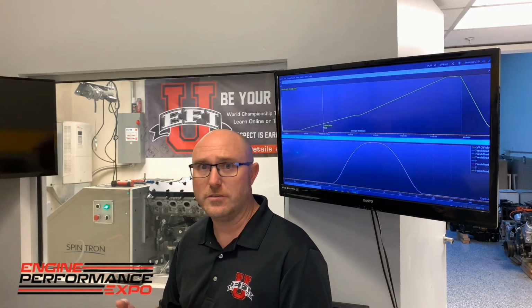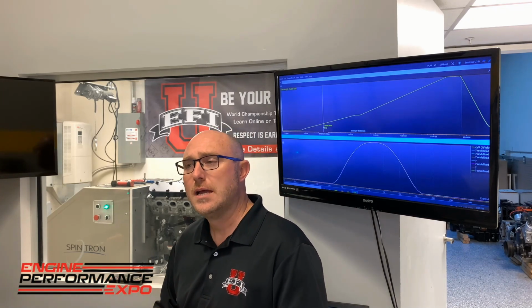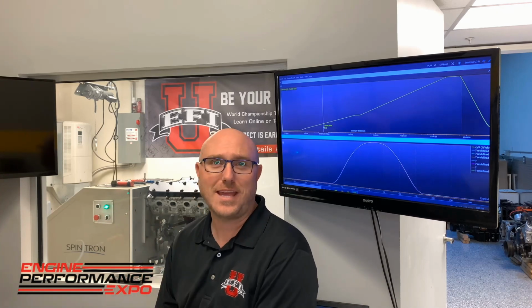The problem is there's a little bit of a disconnect between what we theoretically design. For example, if I get a cam card and look on there, it'll tell me things like valve lift, duration, lobe intake and exhaust centerline angles, lobe separation angles. They give me all this stuff on the cam card, and then I assemble it in the engine, put my degree wheel on, and make sure that it all matches the cam card.